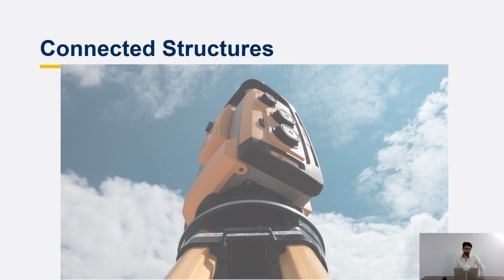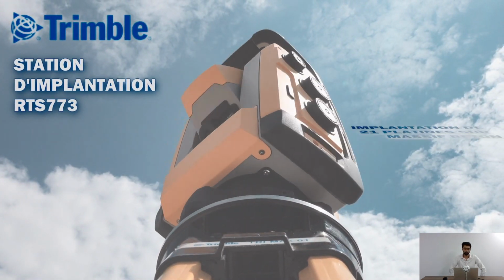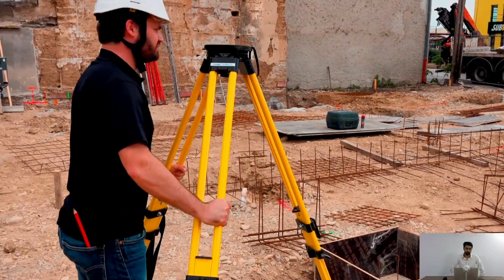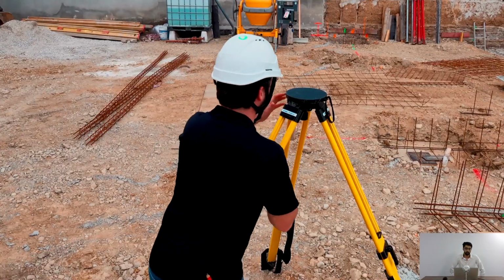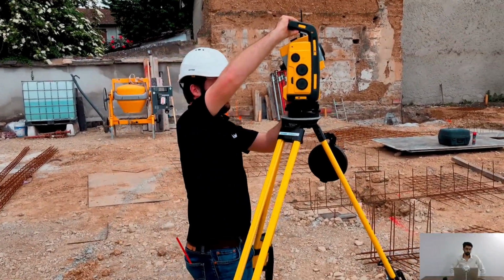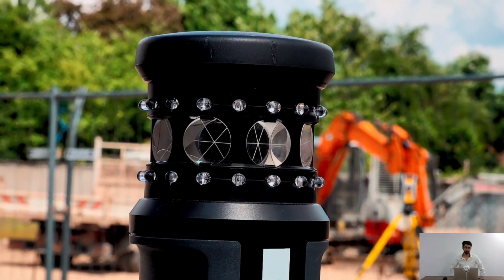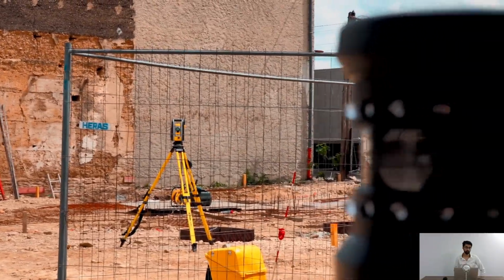Right, so this is a quick video showing you how it works or behaves on site. So basically, let me run that. We'll walk you through it, show you how things are being done. This is actually the robotic total station. You need first, of course, to position it on your site or in your fabrication yard, and then with the help of a specific prism, you'll grab that prism, and the robotic total station will highlight that particular point, which we defined already before using the layout point.